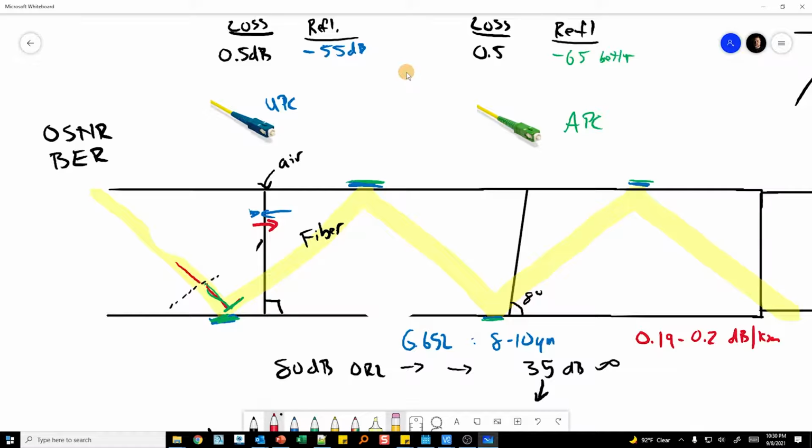So as my signal comes in and it bounces or reflects off of the cladding and it hits that 90-degree angle, it's going to come back at the same angle, right? Like high school geometry, the angle of incidence equals the angle of reflection. And so it comes back at the same angle, which means our reflection is also maintaining total internal reflection. And we don't want to do that. We don't want this signal coming back. We want to break it.